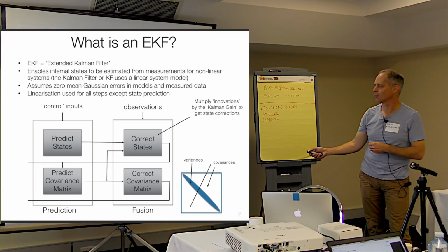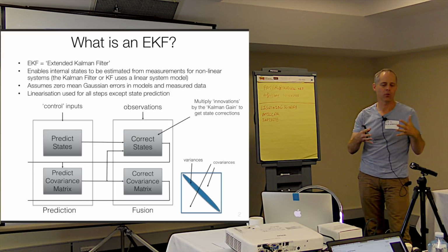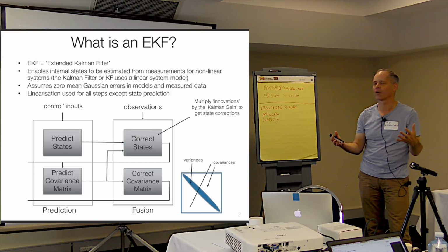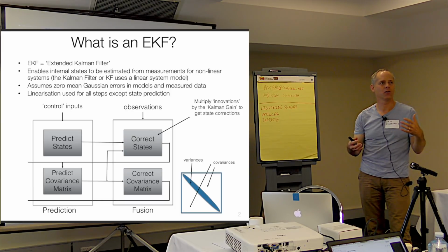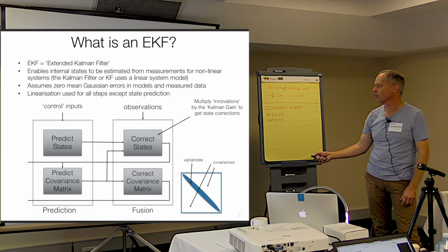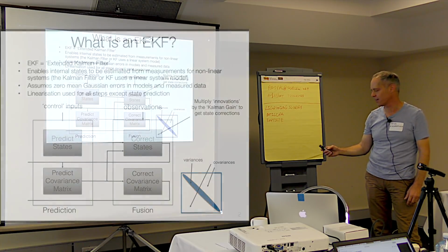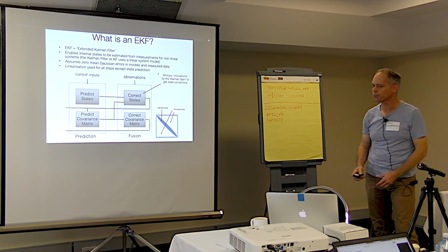There's a big matrix, I won't say much more about it. All the terms along the diagonals, which we can actually get in the logs, represent the RMS error squared. That's one way to think of it for each of the states. The off-diagonal terms, upper and lower, represent how much the error in one state or variable is correlated to the other. For example, how much is the error in your north velocity correlated to the error in your east velocity? That information is captured in these off-diagonal terms. We don't log these terms, so it's pretty irrelevant to log analysis, but they're there for completeness.